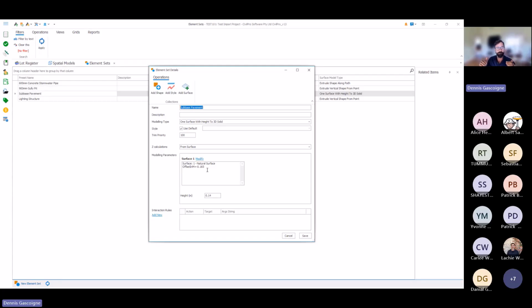So with just one surface, I can actually describe all my pavement layers and create those from the 2D geometries, finished surface TIN, offset height, and I can create a block model from that which contains all the metadata from the lot automatically and generated in the IFC. And that's how we output these. Everything is an IFC, no proprietary formats or anything, so you can import it into whatever you want.